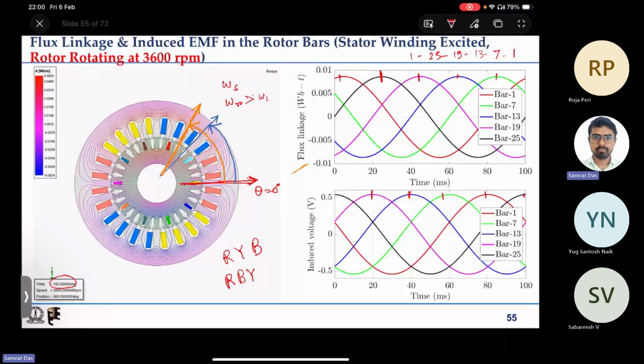Now if we have distributed winding, and if we inject sinusoidal currents of some phase sequence, say RYB, we saw that the equivalent magnetic field rotates, and it rotates in the anticlockwise direction, say. Now what is expected to happen if we inject balanced sinusoidal current of the opposite phase sequence? Then it would rotate in the opposite direction.